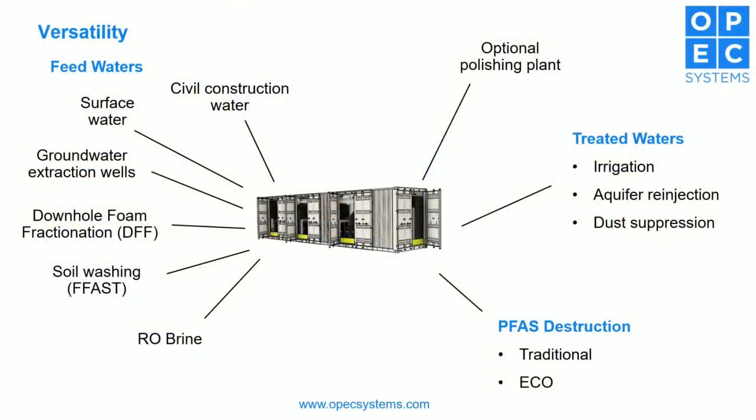And then I guess the last area that we think is important is that a lot of these sites we're going to have PFAS contaminated soil, sometimes in fairly large volumes. And so how do you deal with that? Well, almost inevitably, no matter who the technology provider is, they wash it. They wash the PFAS contamination from the soil and they try to migrate it into a water body.